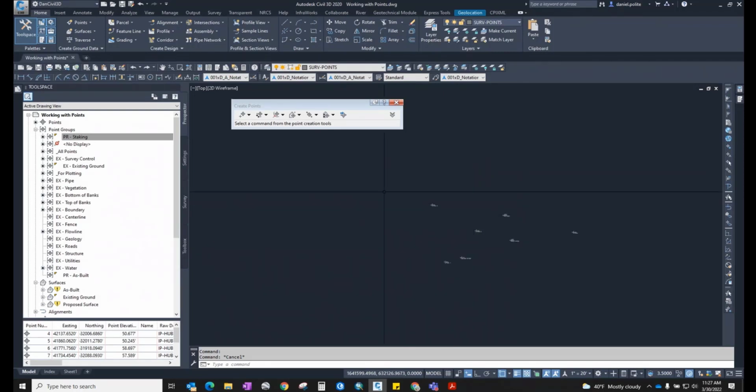So what I like to do when I'm going to stake something out, I always like to make a copy of this. Once it's been completed, obviously with everything on, but at least showing where my points are at. Because keep in mind, when you're setting these survey points up, if you really don't like the person that's going to do the stakeout, set a survey point up, stakeout point here, and then another one way over here, and then another one way over here, and then they'll really like you. But you try to do it in sequential order. Obviously you don't want to do one like that and then one over here and then one down here. You want to kind of keep it as the person's walking along. So if you're set up here, you want to start your survey stakeout points going along here.